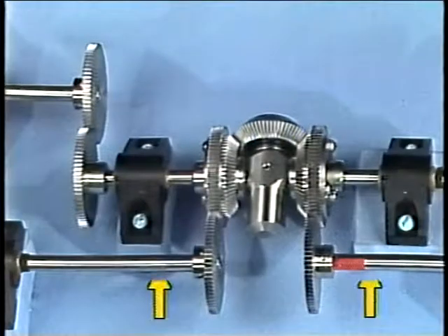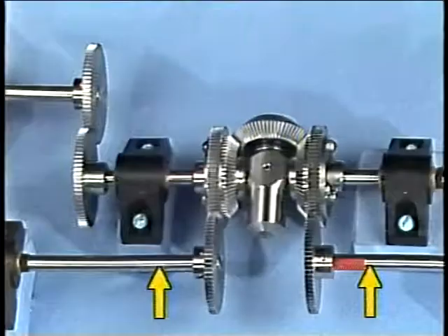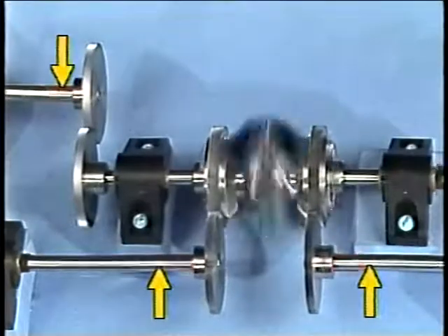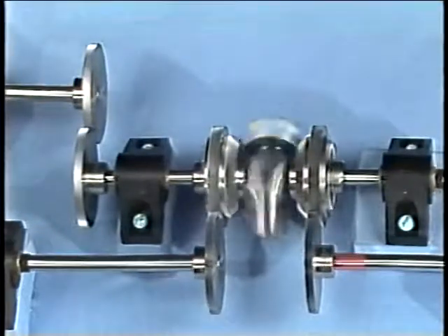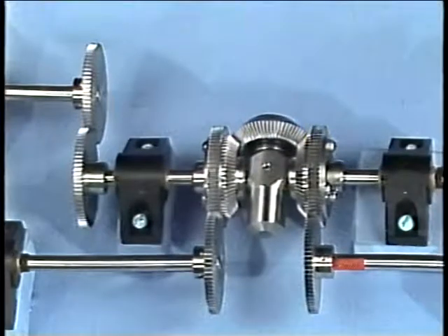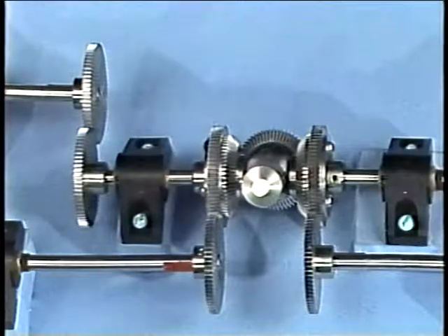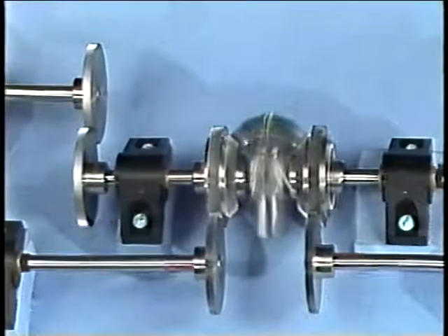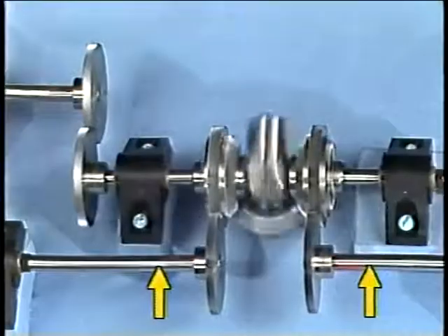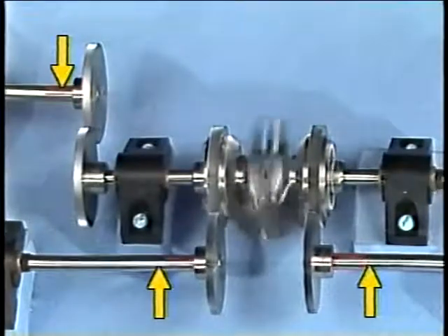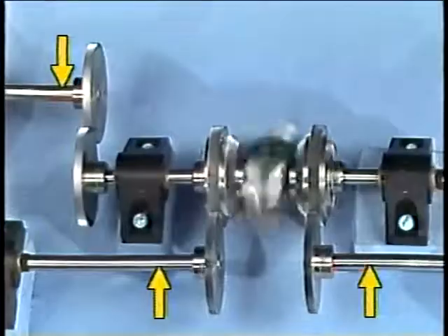Okay, now let's see what happens when these 2 shafts are turned. As you can see, this shaft turns. As we've seen from this example, a differential can have multiple inputs or outputs. Another function that a differential performs that's less obvious is its ability to compare multiple inputs and provide a corresponding output. Right now, this differential is comparing the speed and direction of rotation of each of these 2 inputs and providing a corresponding output on this shaft.